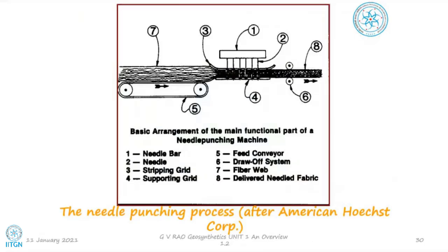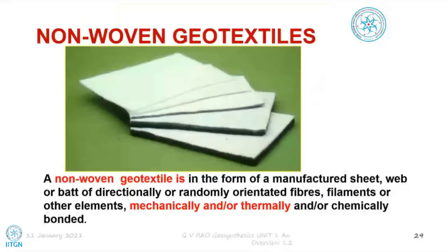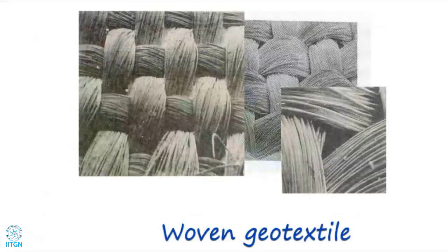So this, of course, obviously, is a strong geotextile. What do you mean by a strong geotextile? When it comes to strength, naturally, we are bothered about a unit for strength. What will be the unit for strength? Normally, what is the strength unit we have? Kilopascal. Okay. Or newtons per millimeter square, whatever it is. That means there is a load or force unit, and there is a cross-section area unit. Now, if you want to define the strength in kilopascals, yes, it's very good.